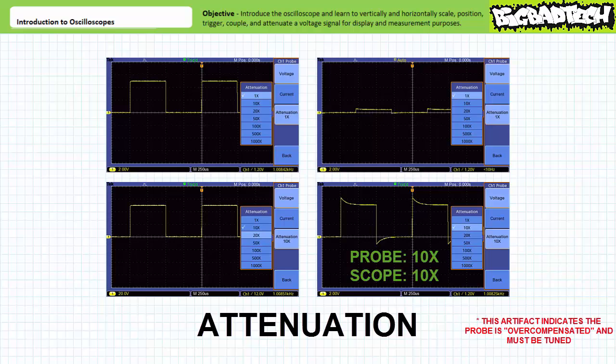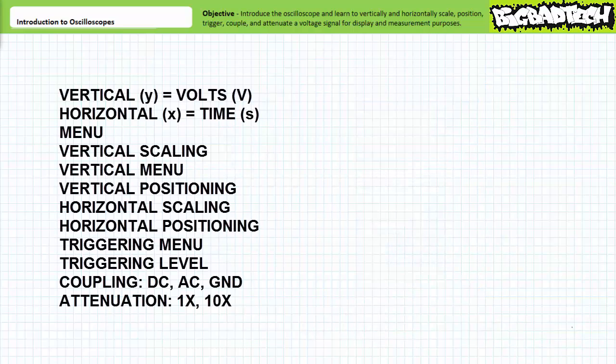Although the display does show some artifacts at the corners. Finally, given all the user-adjustable features in an oscilloscope, often the source of errors is not the current user, but rather the previous one. If the previous user happened to set up the oscilloscope with an odd vertical and horizontal sensitivity, position the trace bizarrely, use some abnormal triggering condition, attenuated it weirdly, or performed some other advanced option like